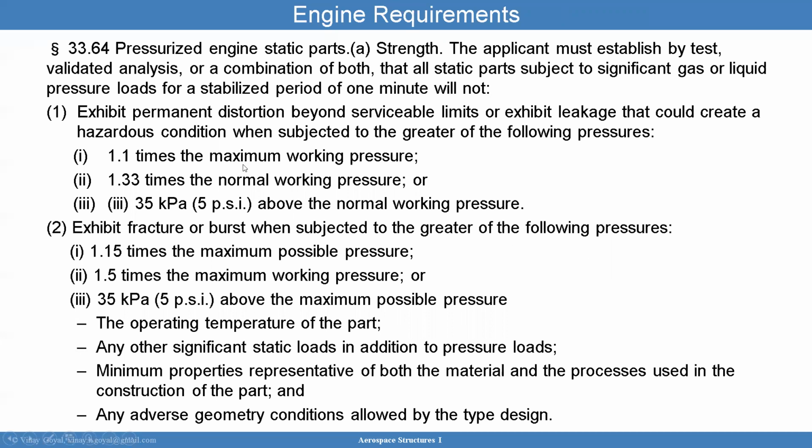You're looking at 1.1 times the maximum working pressure, 1.33 times the normal working pressure, and then you also want to make sure that you don't exhibit fracture or burst when subjected to the greater of the following pressures: 1.15 times the maximum possible pressure, 1.5 times the maximum working pressure. So this one here is for leakage and permanent distortion, and this one here is for fracture or burst.